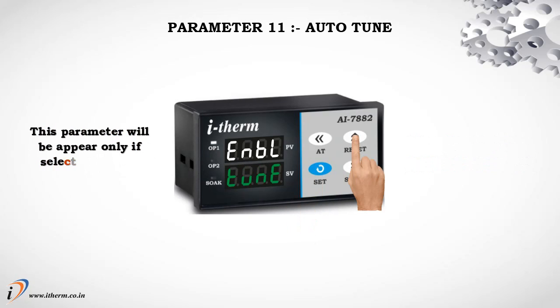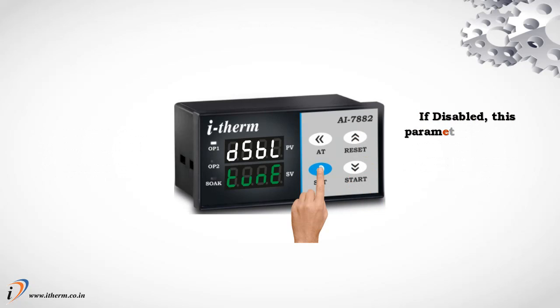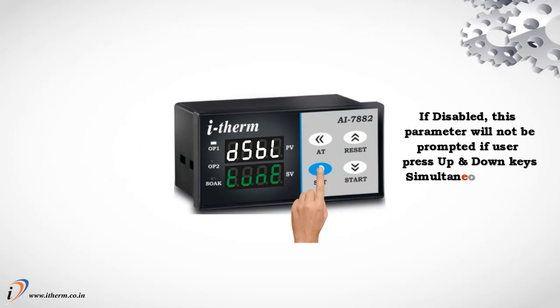Parameter 11, Auto tune. This parameter will appear only if the selected control action is PID. If enabled, this parameter will be prompted if the user presses the Up and Down keys simultaneously for 3 seconds. If disabled, this parameter will not be prompted if the user presses the Up and Down keys simultaneously for 3 seconds.